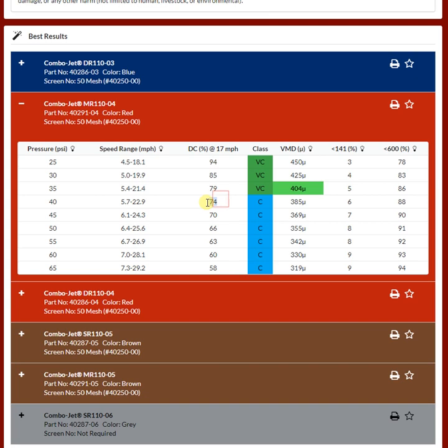So 74% duty cycle is just the percent of that duty cycle at your max speed. As far as a rule of thumb, a good place to be is usually around that 60 to 80% duty cycle. The reason it is more of a range rather than just a single number is because there's a lot of leeway. So typically there's not much penalty for operating at a little bit higher duty cycle, a little bit lower. There's typically only 2 penalties.